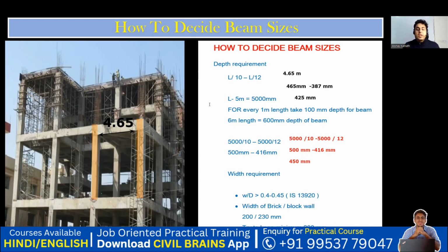Pretty simple. Now coming to the width of my beam. Depth I've decided. What about the width of my beam? For the width, you can usually go with the thickness of a brick, because if you see, this is my construction. We do brickwork or blockwork here, right? And the thickness of a brick is usually 9 inch, which comes out to be 230 mm. Or sometimes we use an 8 inch block, which comes out to be 200 mm. So usually whatever my brick size or block size is, that will be the width of my beam. If you're using a 9 inch brick, the width of your beam will be 230 mm. And if you're using an 8 inch block, the width of your beam will be 200 mm.